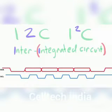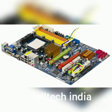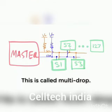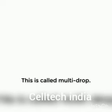I2C and the very similar SMBus are in almost everything. You'll even find it as a major part of computer motherboards. The interface allows communication with up to 127 devices with only 2 wires. For many sensors, I2C is the standard way to get data.